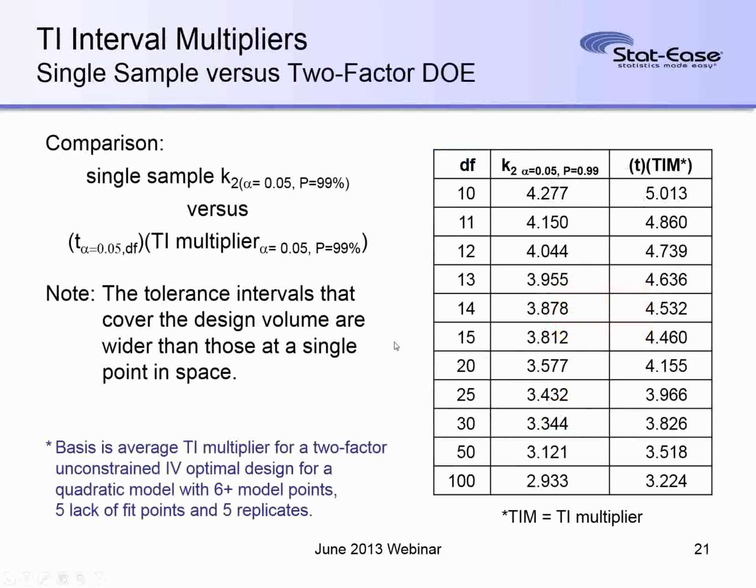That's just how it happens. That helps us decide whether or not we can even meet with any design a certain tolerance requirement. If your tolerance requirement goes too short, it is not possible to solve a tolerance interval that will include 99% of the population. It's one of the rules of statistics.